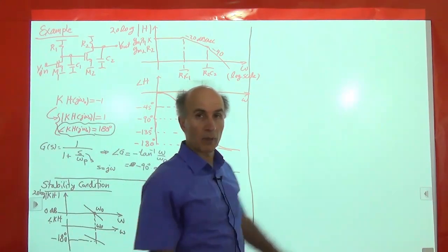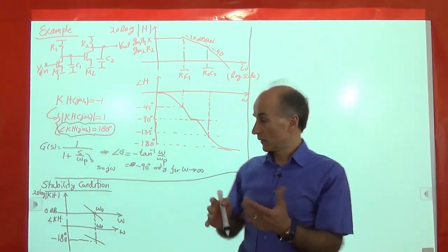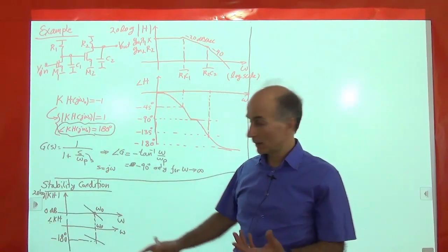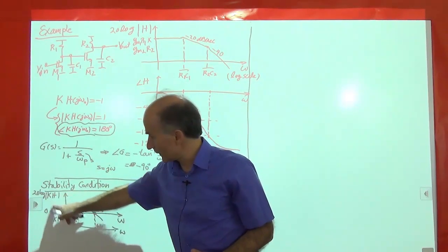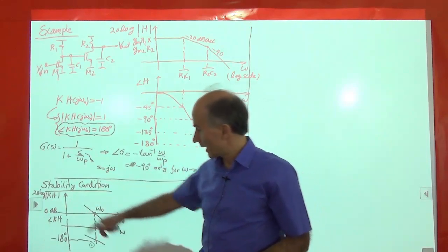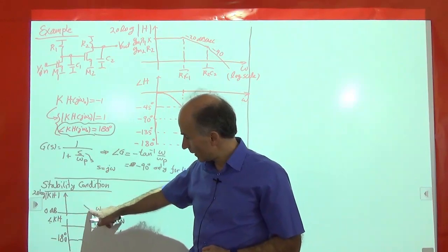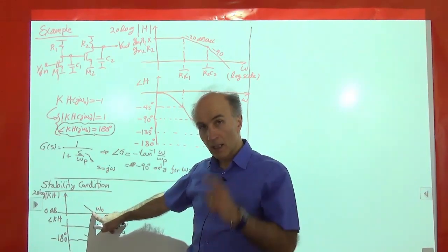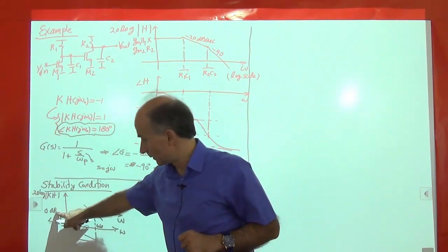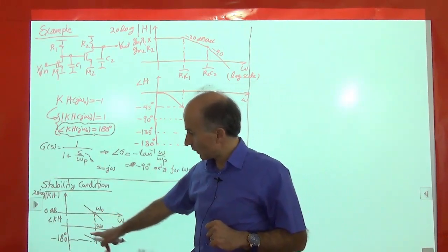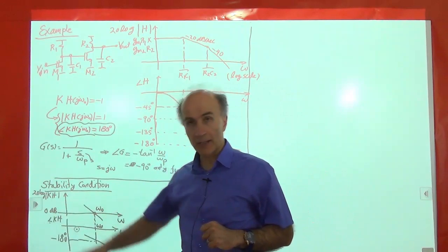Okay, so I bought an amplifier. I assume some K, whatever you want, maybe 1, right? And then H belongs to the amplifier. I can construct this frequency response. It has some stuff here, we don't care. We just go and see where the magnitude is crossing a value of 1, meaning 0 dB, right? And it's some frequency. And then we also plot the phase of that transfer function.